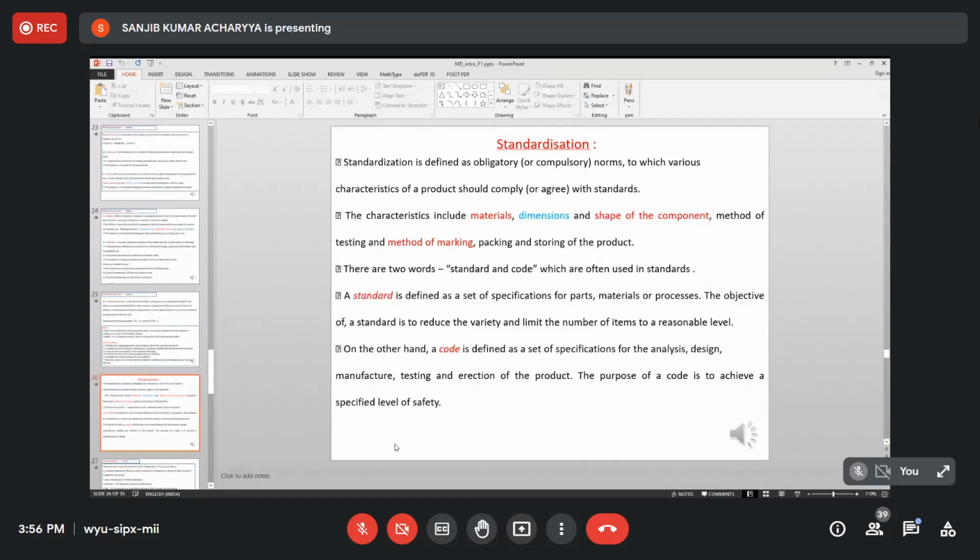Dimensions. Different standard parts like bolts, nuts, shafts, etc. Any dimension is not available in the market. Only certain dimensions are available in the market. The variety is to be reduced because variety increases the production cost. Therefore, we have to manage the total demand. Demand is a continuous spectrum. Somebody can require 15.5, somebody can require 27.8, somebody can require 15.6. But if the manufacturer is to supply 15.5, 15.6, like each member, then he has to produce an infinite number of products of dimensions, which is impossible.